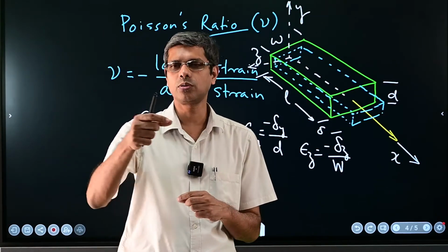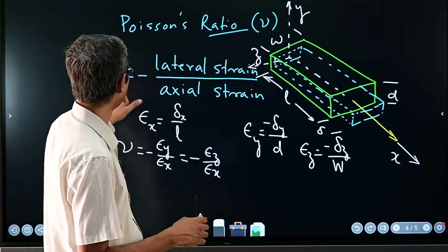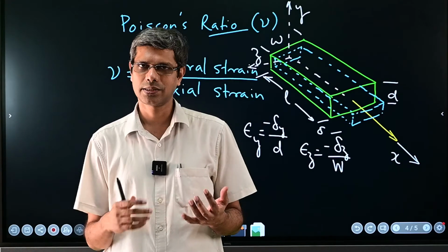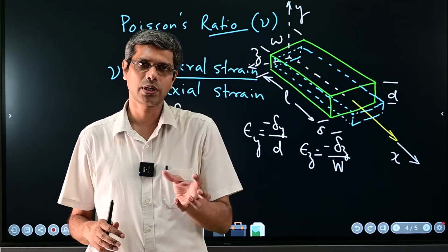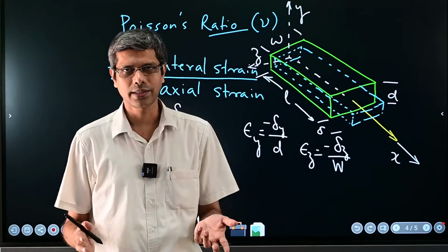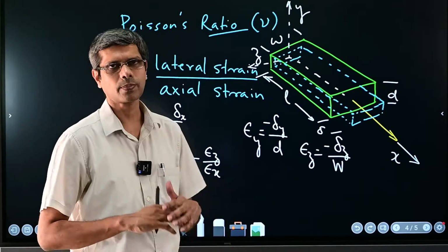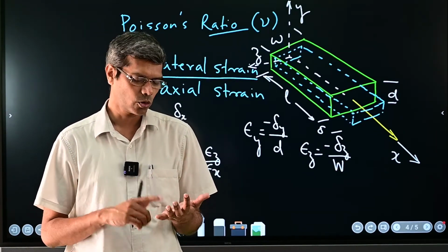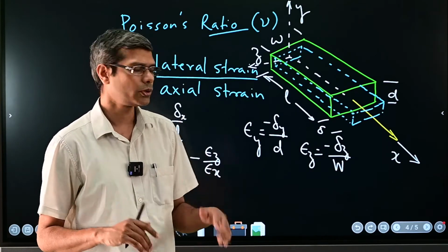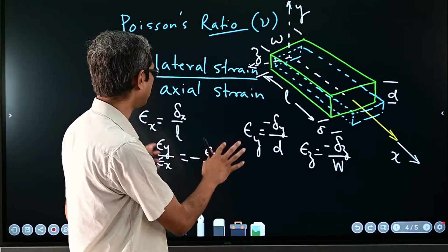That means from point to point, if we change in space in the material, the value of the Poisson's ratio doesn't change, so that's the homogeneous property. And if we change the orientation of our axis, again nu doesn't change, so that's the isotropic. So for us, all the materials that we will deal with in this course will be homogeneous and isotropic. So you have to think of these two properties whenever you use them.